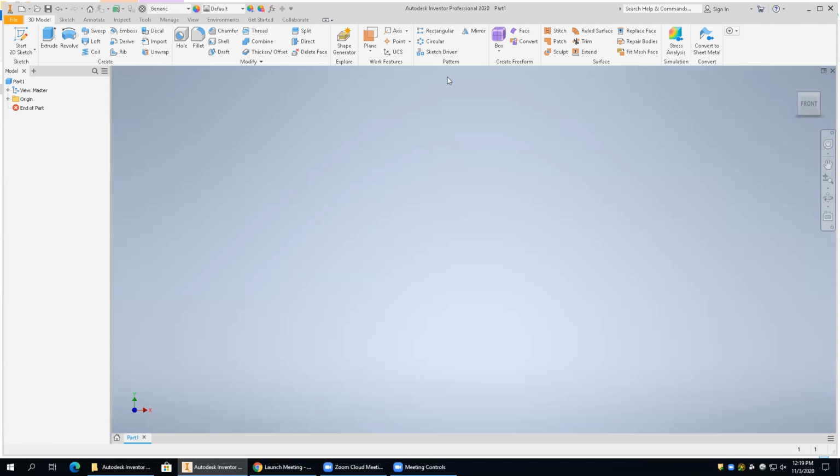All right, so this is your workspace area that you're going to work in. It's fully three-dimensional. It's called your graphics window. Okay, that's where most of our action will happen. It's equivalent to what you would call model space in AutoCAD. Down below here, you have this little guy. We called it the UCS icon. They call it the 3D indicator. Okay, it's the same thing. It has the same function. That's going to be really important to you in Inventor. Okay, you're going to utilize that a lot.